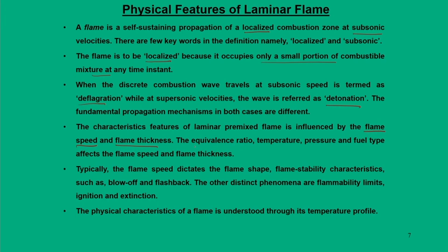For a self-sustaining flame, we require adequate equivalence ratio, temperature and pressure, and fuel types; all conditions need to be satisfied. In fact, the flame speed effectively dictates the flame shape and stability, such as blow off and flashback. Blow off and flashback mean either it can create an explosion, or the flame will be out of the domain, or the flame will not exist.